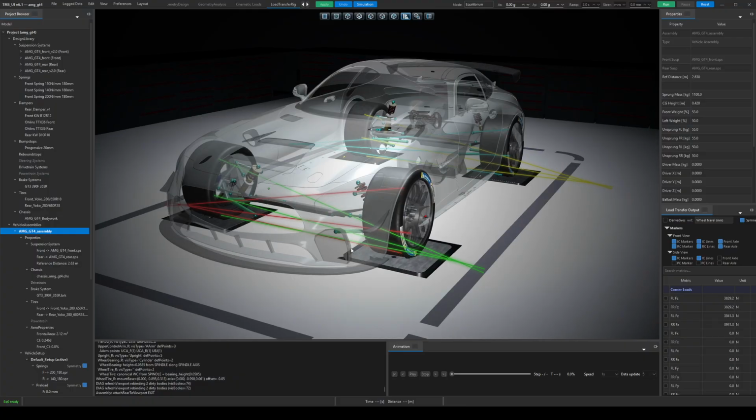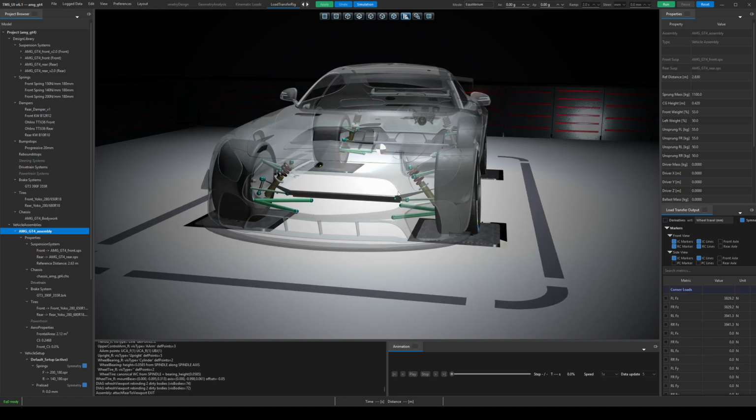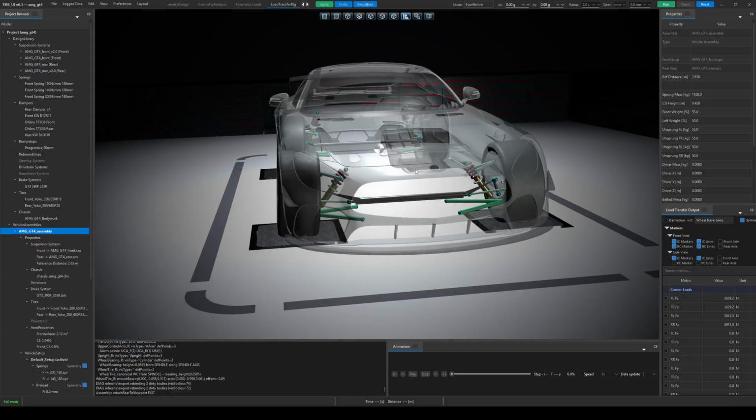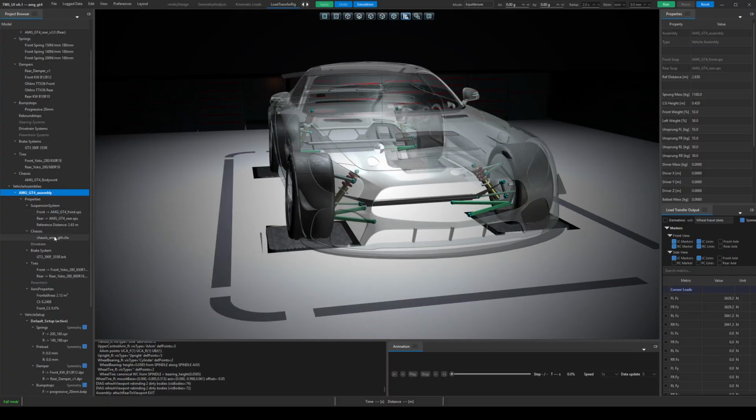This is where the application moves from kinematic suspension geometry into dynamic multi-body simulation. The vehicle assembly now has mass, inertia, constraints, elastic elements, dampers, and time-dependent applied loads. In other words, this starts to move into the same general territory as tools like Adams, SimPack, and similar multi-body dynamics packages, but with a workflow focused specifically on race car setup and suspension design.